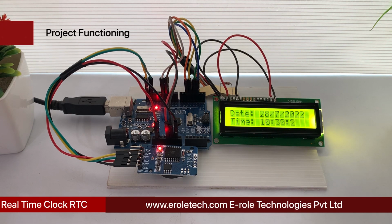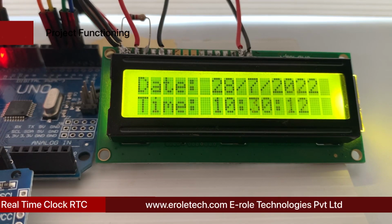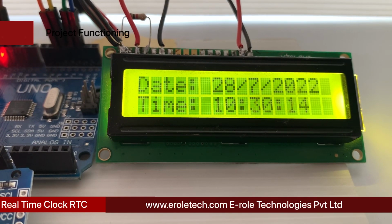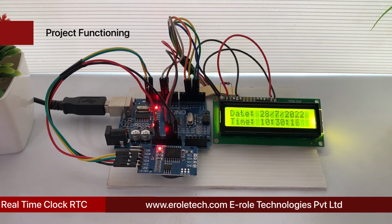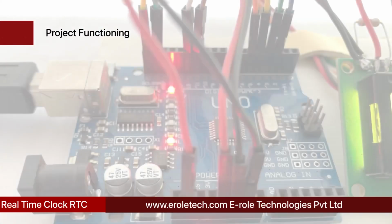RTC, or real-time clock. As its name suggests, a real-time clock is used to keep the record of date and time. It is used in many digital electronic devices like computers, digital smartwatches, data loggers, and situations where you need to keep track of time. One of the great benefits of a real-time clock is that it can keep the record of time, even if the power supply is not available. Almost all RTC modules come with a small coin-sized 3-volt lithium cell, which can work for years.